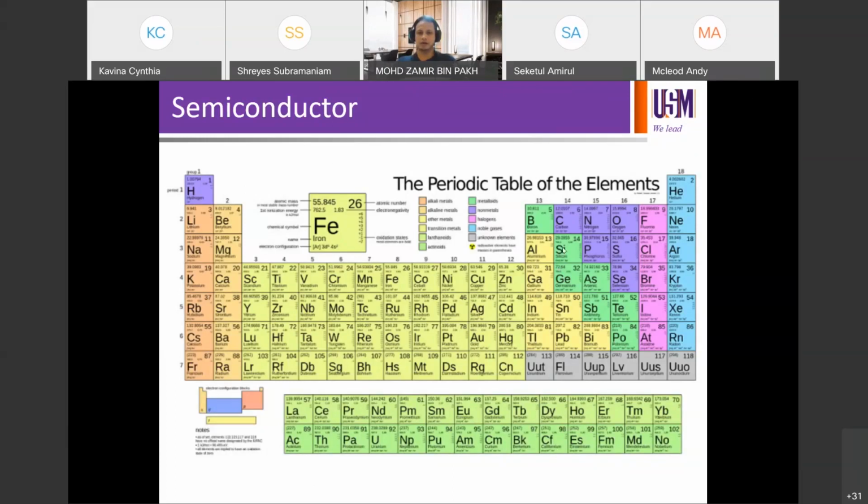Okay, so silicon, you have carbon, germanium, tin, lead. So in this course, we're going to talk about silicon a lot as the host atom. And then when we talk about doping later on, we're going to talk about dopant atoms relative to the host atom, which is silicon. Then we're going to discuss which one has extra electrons, which one will provide extra holes in order to improve conductivity of the silicon.